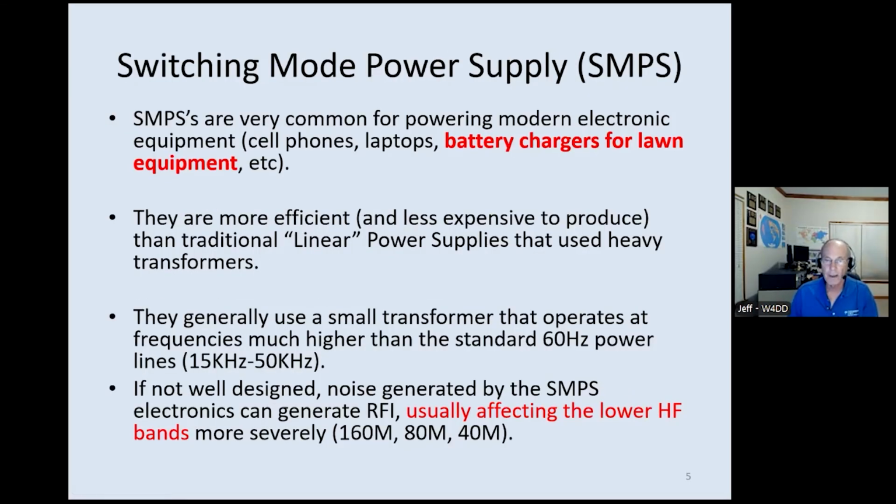Switching mode power supply, different animal. SMPSs are very common for powering electronic equipment nowadays. You see very few linear power supplies, almost all SMPSs. And one of the ones I see very frequently is battery chargers, usually used on lawn tools, sometimes on dust busters. If it charges a battery and it's a high current SMPS, they generally make noise. And I find them almost anytime I go out and do an RFI assist.